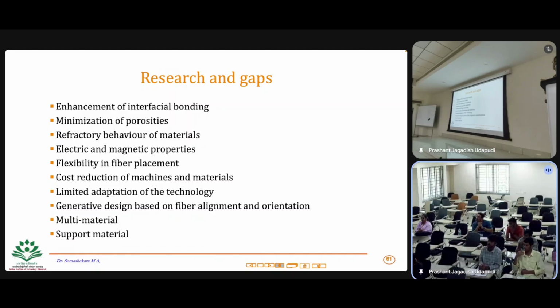And then using the right material. And as I said, you don't need to try to decrease too much. Otherwise, if you decrease too much, you will end up spending more time in printing. There are a few other ways, but I think these are the major parameters that affect bonding between the layers.